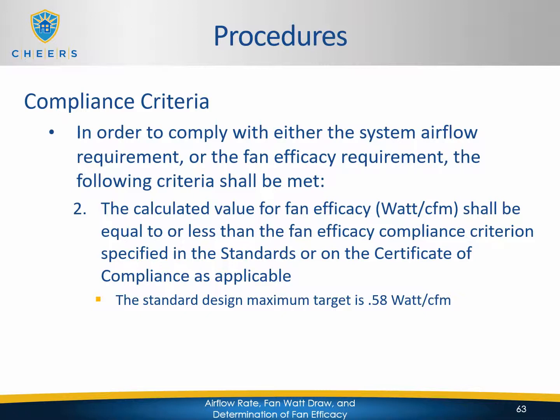The calculated value for fan efficacy, which is the watt per CFM measurement that you took, that you calculated, shall be equal to or less than the fan efficacy compliance criteria specified in the standards, again, or in the certificate of compliance, which is the CF1R, as applicable. And as I stated before, the standard design maximum target is 0.58 watts per CFM. And again, always refer to the CF1R to find the specific requirement for your project.